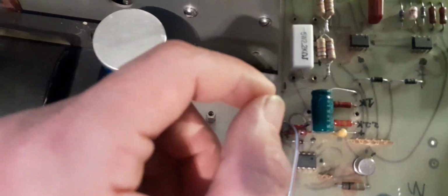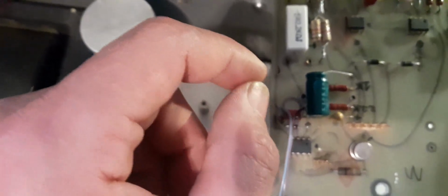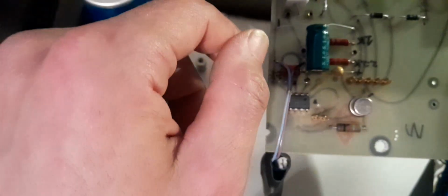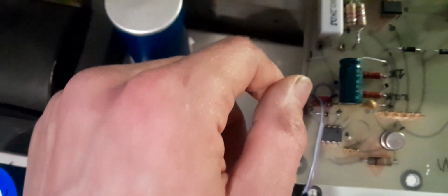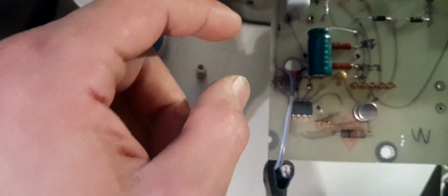Then I can just put a TL431 and a couple of capacitors in there, and on the bottom of the board fold the leads over to form the traces and solder the leads to those 2 traces. I hope that makes sense. Oh, and the trimmer pot will maybe just get tacked across the top. I haven't thought about it yet, but I definitely want to try and incorporate it into the board somehow, so it's not just flapping around in the breeze.